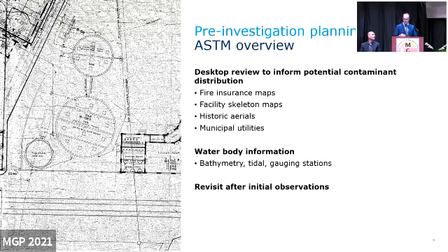There is a tar tank here in the lower corner, and you can't see it on the screen here, but there is a tar sewer that's called out on the skeleton map that connects from that tank to the adjacent water body. So that was obviously a location where we had to plan some investigation at this particular site. Historic aerials can be pretty helpful, not so much in terms of determining where processes may have been located,